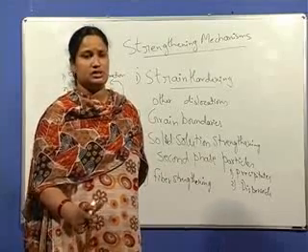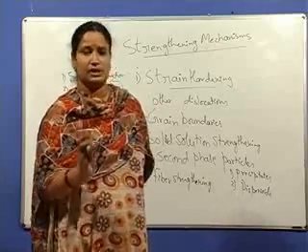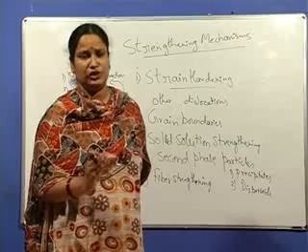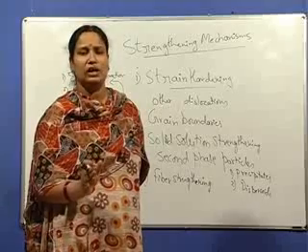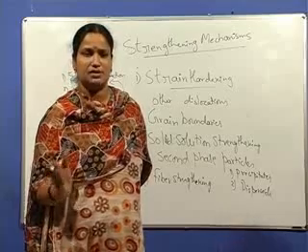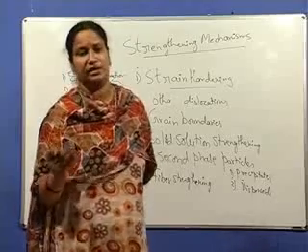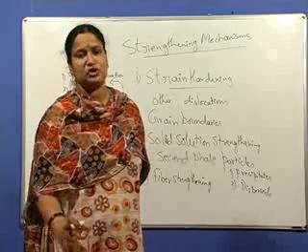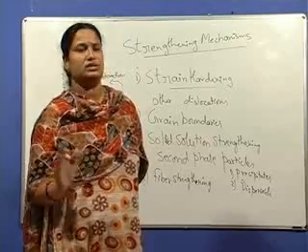So these distortions hinder the motion of both edge and screw dislocations in the case of interstitial solute elements, whereas substitutional solute elements, which cause only spherical distortion, hinder only the edge dislocations. More distortion is caused by the interstitial solute elements, thereby greater hardening when compared to substitutional solute elements, which cause less distortion and thereby less contribution to hardening.